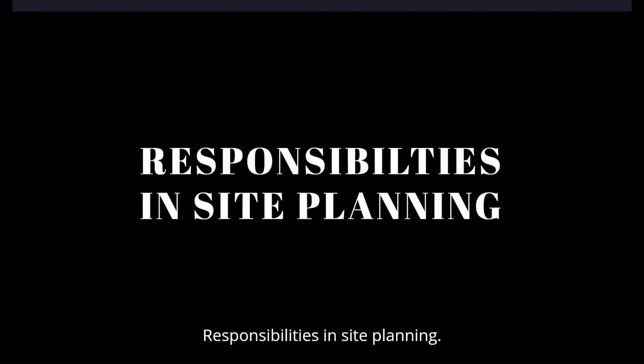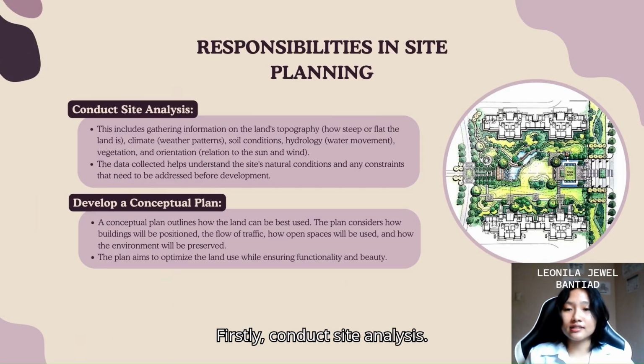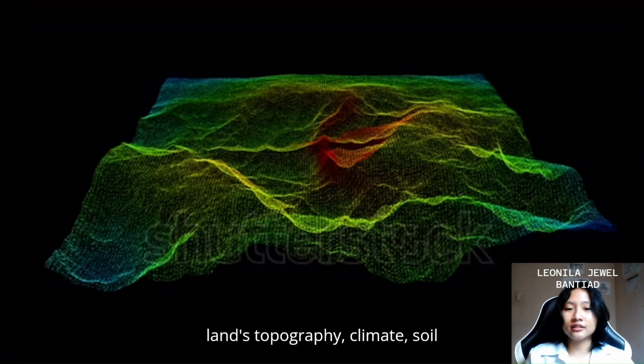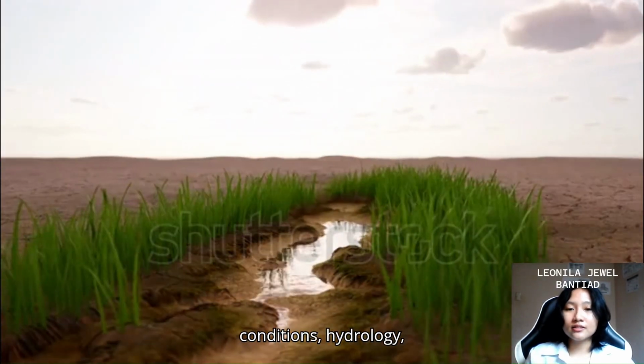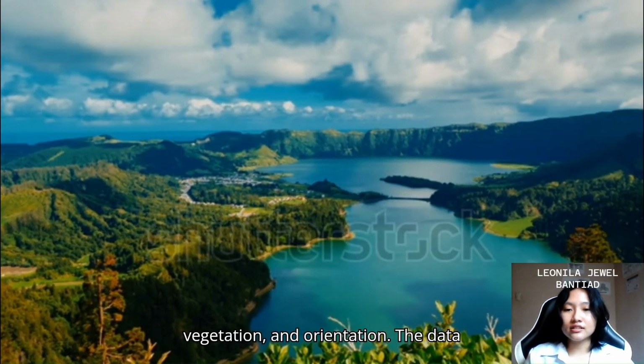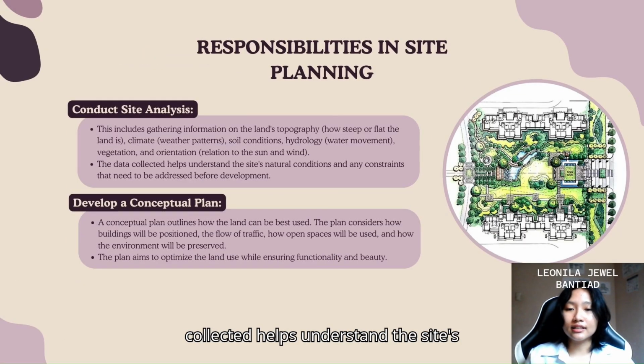Responsibilities in site planning. Firstly, conduct site analysis. This includes gathering information on land's topography, climate, soil conditions, hydrology, vegetation, and orientation. The data collected helps understand the site's natural conditions and any constraints that need to be addressed before development.